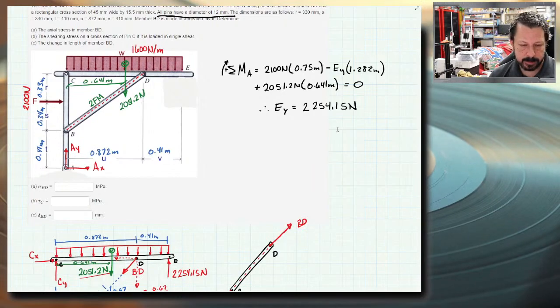Even then, you would have 1, 2, 3, 4, 5. Yeah, you could do it then. You'd have 6 unknowns because you'd have dx and dy, and you'd have bx and by that you don't know. And you'd have to write the entire set of equations, 3 each, for member CDE and for ABC, and solve this thing simultaneously. So it could be done, but it would be much more difficult.